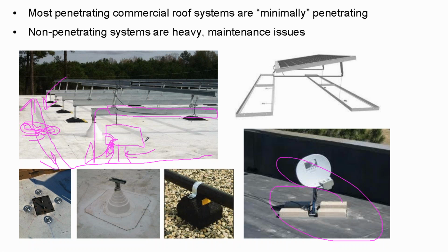solved. We do floating solar arrays that are not positively or negatively grounded. Instead, they're functionally grounded. So all the metal parts are still grounded. We're just not connecting the negative pole of the inverter directly to ground anymore, fusing both ends. But in this one particular circumstance, it was causing commercial solar arrays where you'd have multiple circuits wired together to start feeding into the ground faulting circuit, which is only sized for one circuit's worth of power, not 20 circuits worth of power.